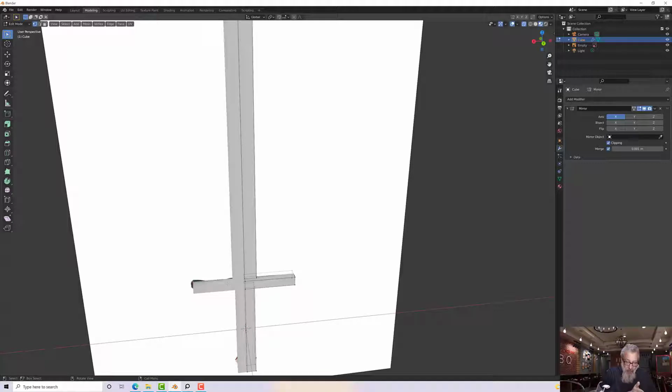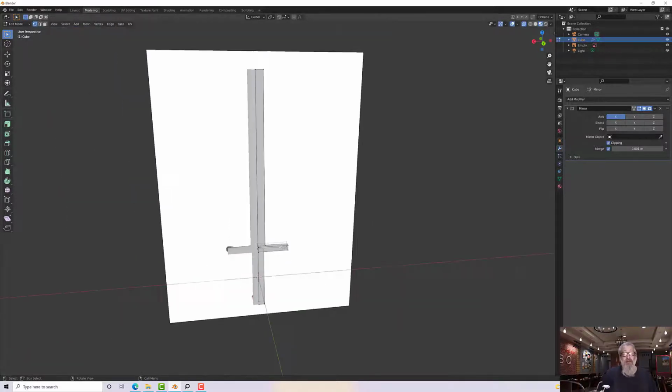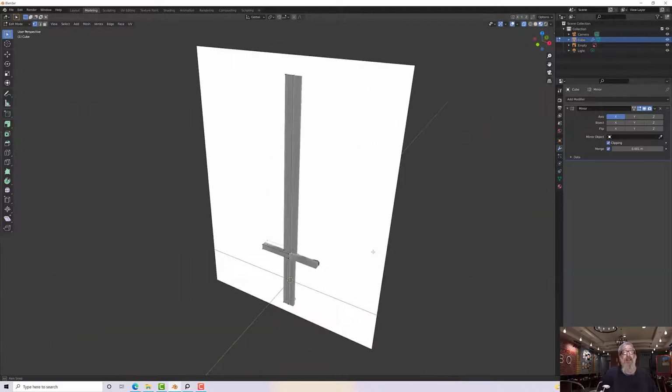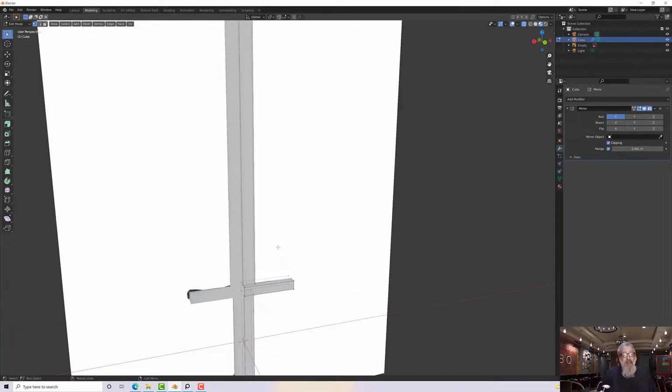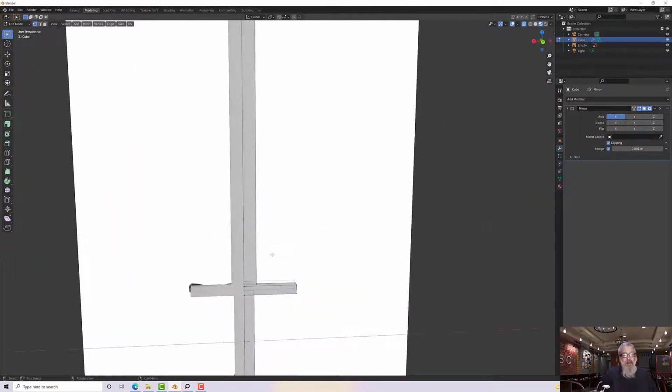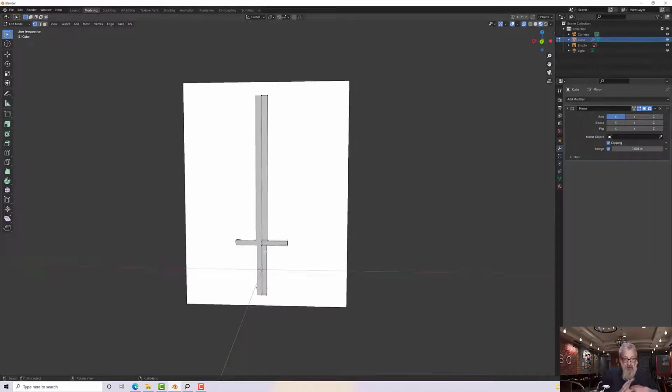It will just stop it dead in the middle. If clipping is off, you can move too far to the left or too far to the right and it can cross the geometry and gets confusing. So in general I have clipping turned on at that point in time. So that's set up our mirror, and in the next video what we'll do is actually start to add some geometry to put some shape in.